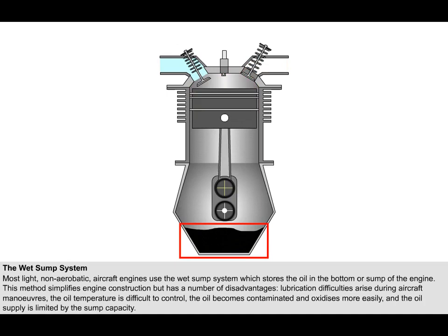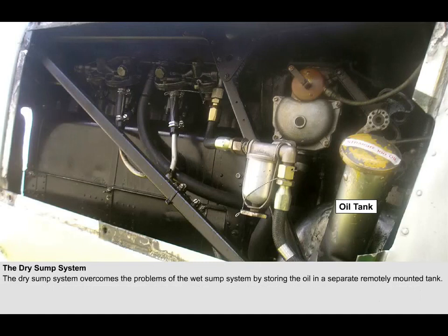Finally, the oil supply is limited by the sump capacity. The dry sump system overcomes the problems of the wet sump system by storing the oil in a separate remotely mounted tank. However, this type of system does have the disadvantages of being heavier and more complex.